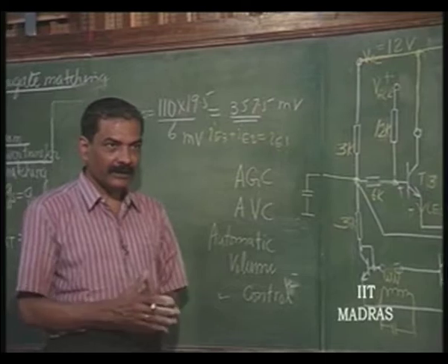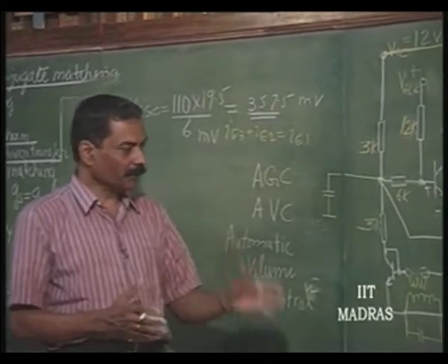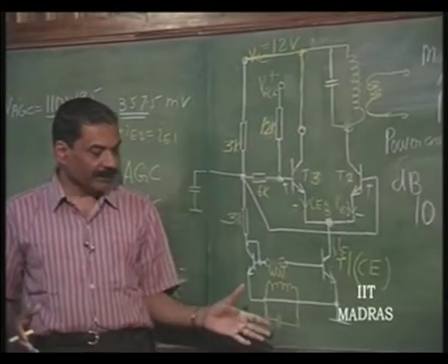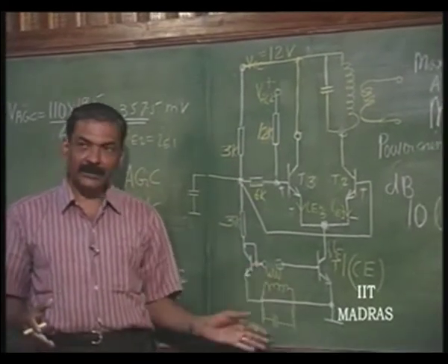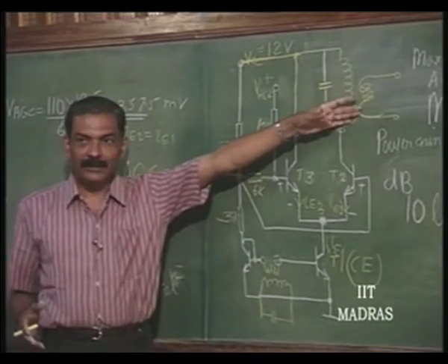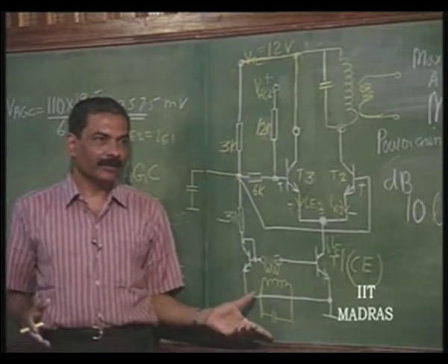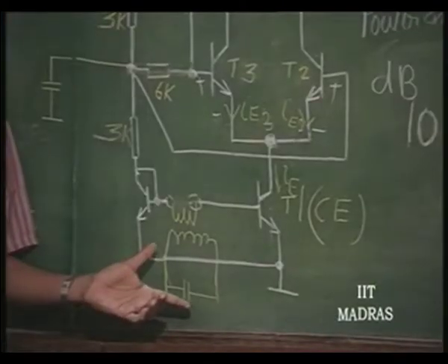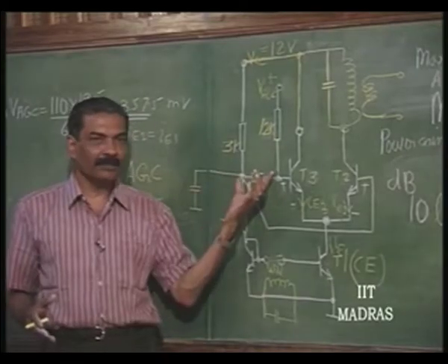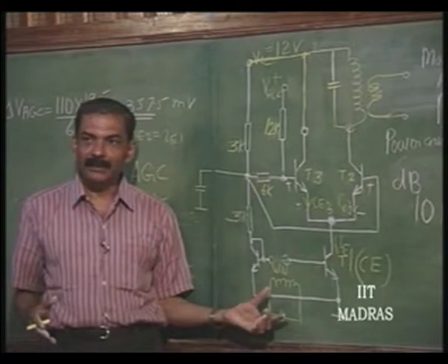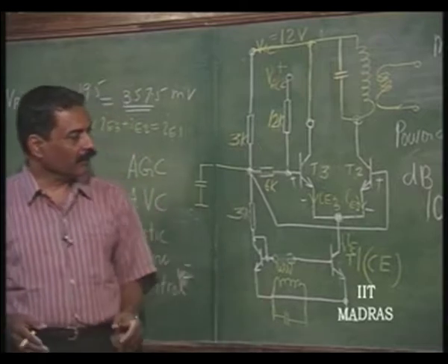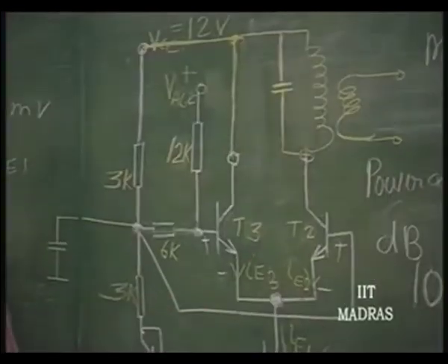depending upon the frequency of interest to you. So, correspondingly a tuned circuit at the input and a tuned circuit at the output can be put. If it is an IF stage, this is IF and that is IF. If it is a mixer stage, this is IF, but this is a mixture of local oscillator frequency as well as the incoming frequency. The incoming frequency can be given here and the local oscillator frequency can be given here, because this acts as a multiplier or a modulator, and therefore, it is also used for a mixer.